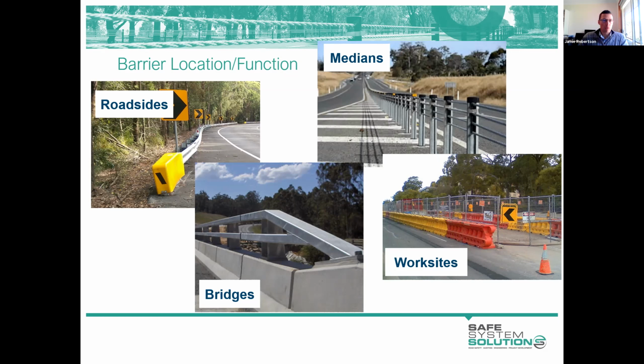So in those cases, we generally would seek to provide the most flexible barrier system that we could. If we're at a bridge or a median where there is perhaps a greater consequence if the vehicle penetrates that barrier and ends up on the road or the waterway below, or enters into oncoming traffic, which might particularly be an issue in a high-speed urban freeway environment, for instance, and we might beef things up to concrete.